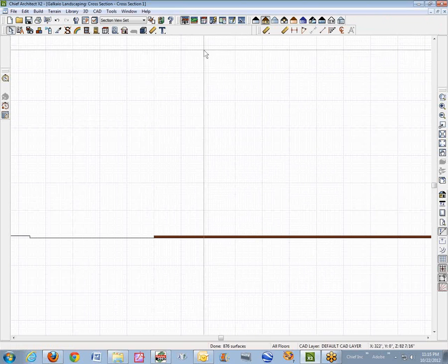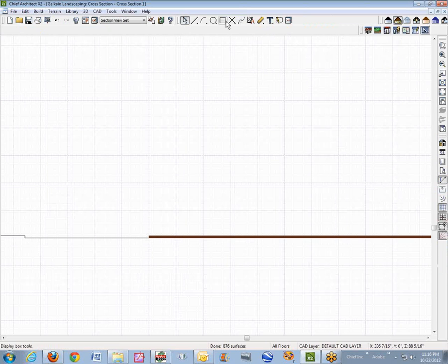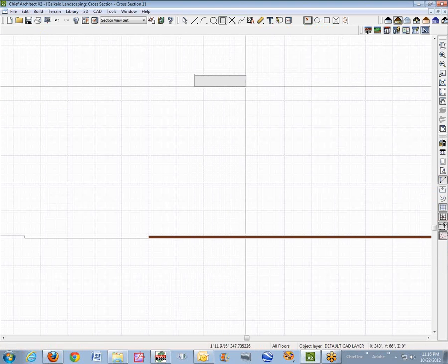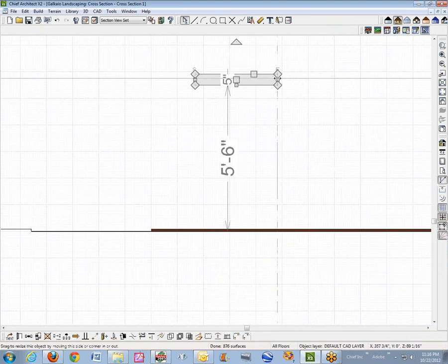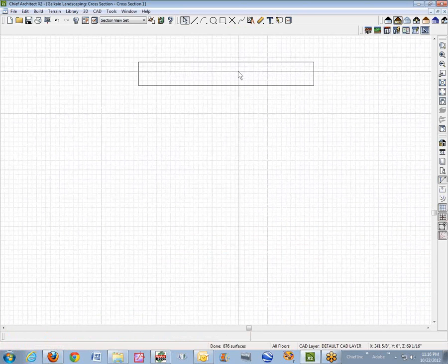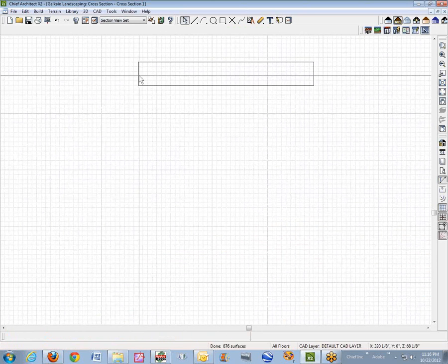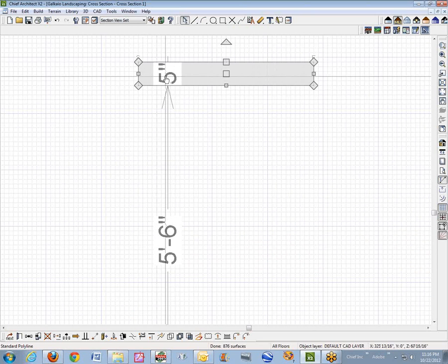And I need to be in the two-dimensional toolbars, yeah, there it is, CAD configuration. And I'm going to draw a closed polyline. That's a closed polyline. A polyline is just two or more lines that are connected. And in this case, we have a 4-line polyline object. 1, 2, 3, 4. And I'm just going to make this 1/8 of an inch thick.